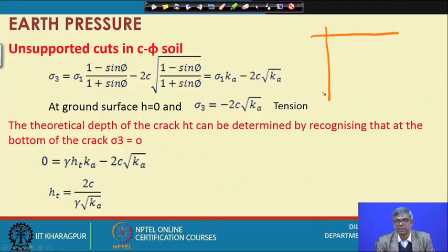And for this excavation, obviously if you know the soil is sandy, then we cannot do any excavation without support, because as soon as we cut, the soil will flow and come into the excavated portion. But if the soil possesses some amount of phi, generally you can cut vertically up to some depth. Okay. So, that depth is what we have to find out.